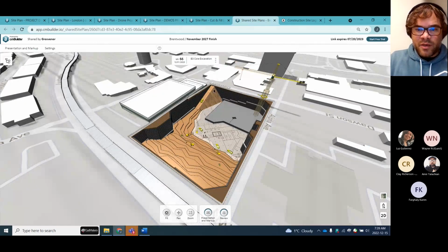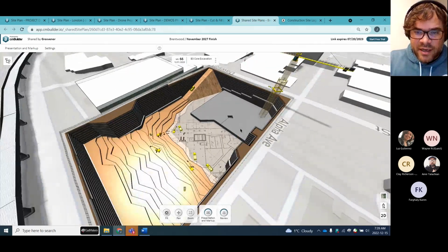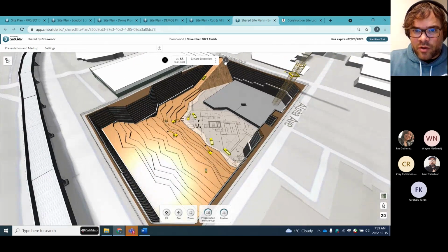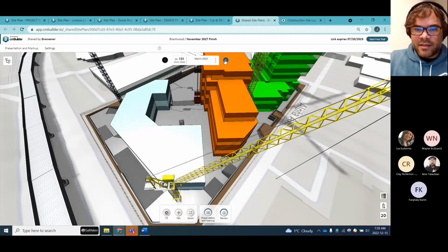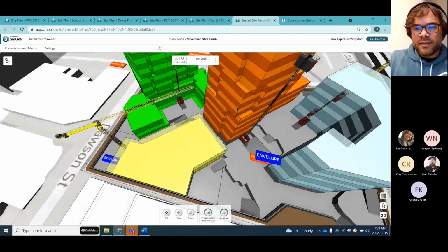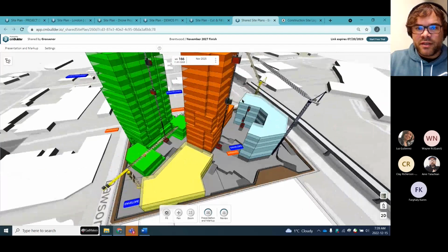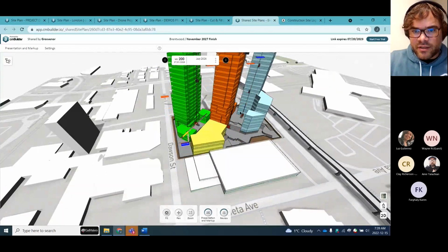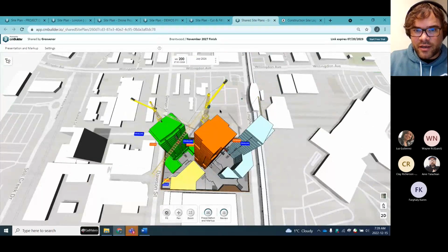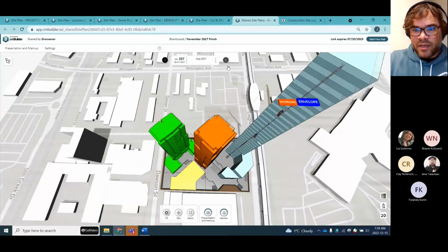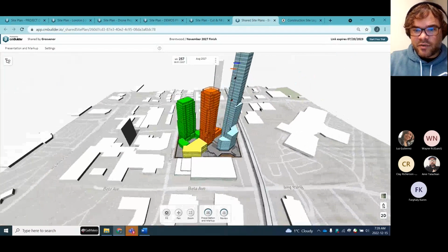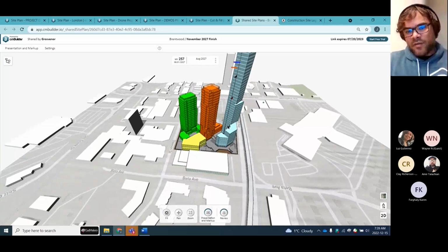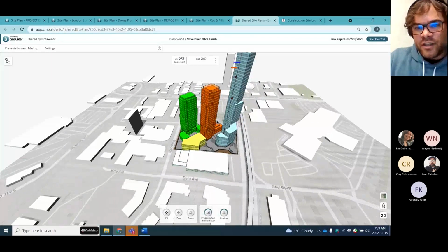For example, this big one, this is a big job where they had a schedule, they had some drawings, the BIM model wasn't quite ready yet. So you can just get really creative with the massing, right? And this is a big job with multi-towers and multi-cranes. There's a lot of consideration on crane location, how do you get cranes in, how do you get cranes out, making sure things aren't boom bound. So this is all done 100% inside with the massing, right? So you basically snapped all the floor plans of each of the towers and you created this. So you can get pretty creative.